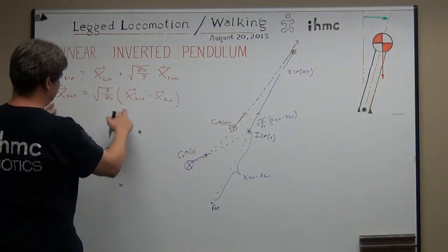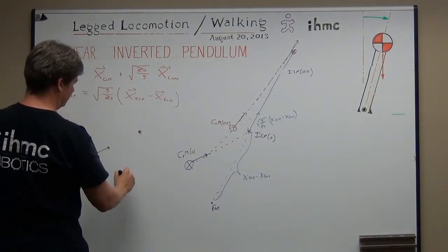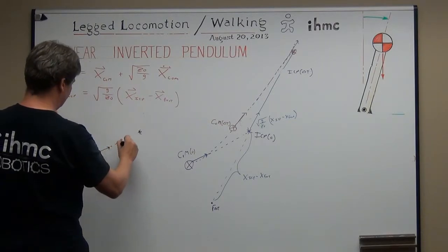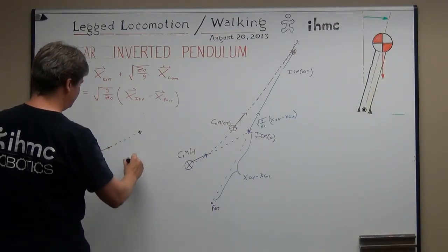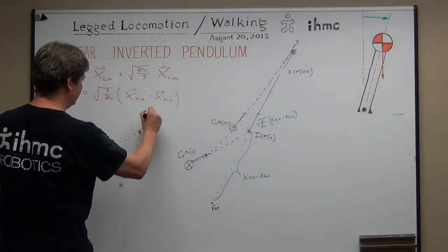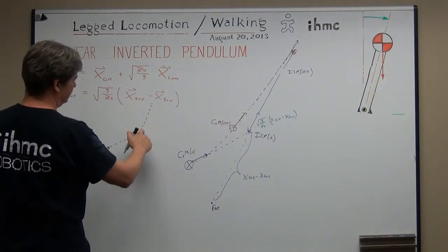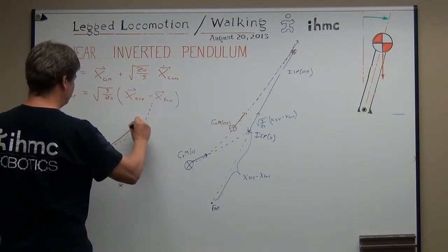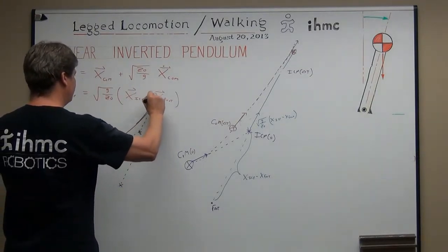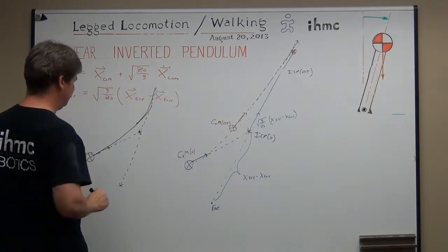Using this instantaneous capture point equation, the point is ahead on that straight line of that velocity, somewhere there, exactly what I drew here. Then you take a line from the foot to the instantaneous capture point, and that's the way the instantaneous capture point will move. It will be hyperbolic from there, and it'll never quite reach it.